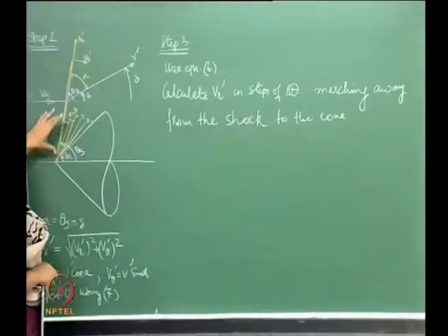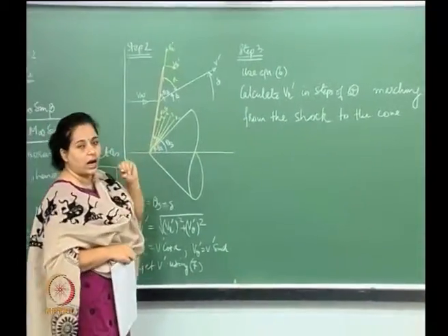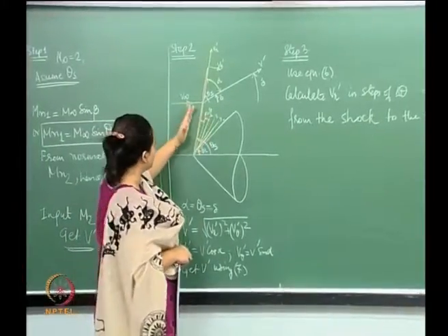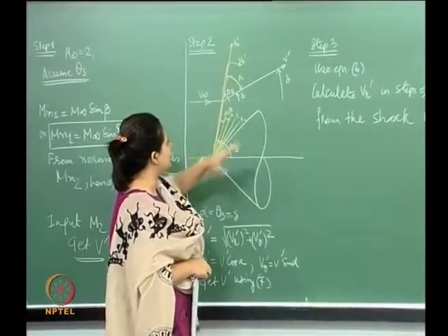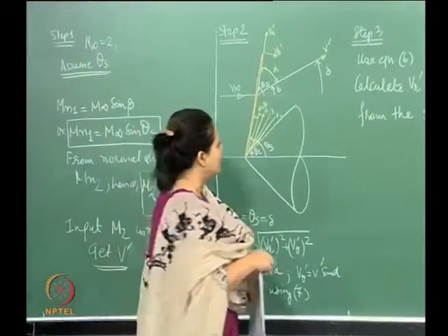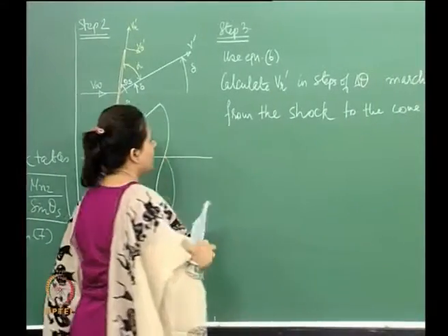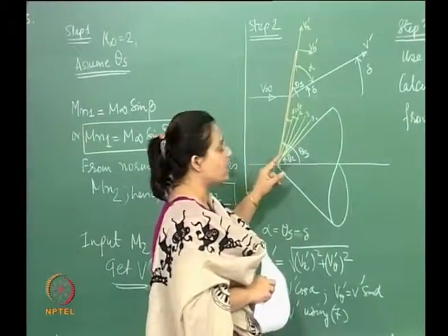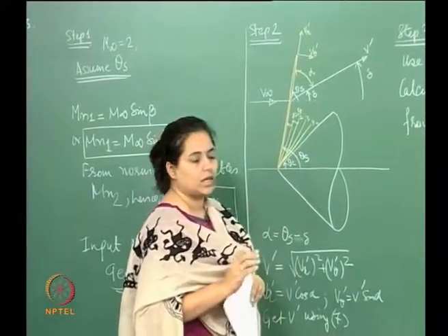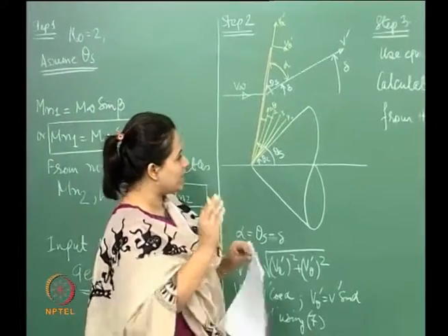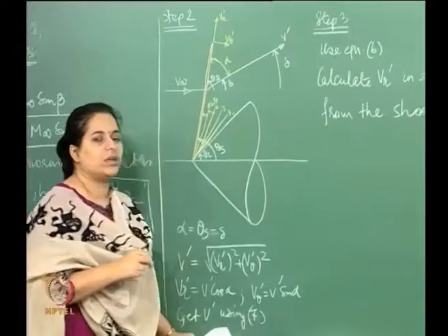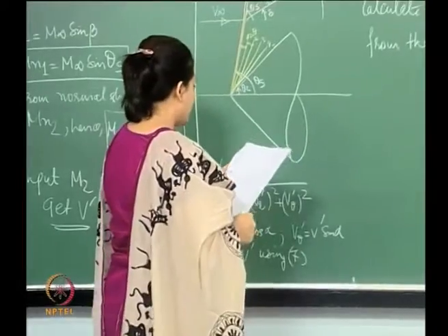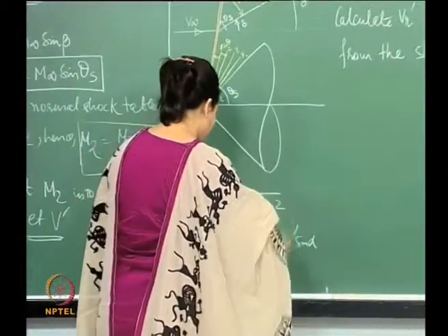Okay. So, basically which means that we will calculate the v r at various radial lines between the shock and the surface of the cone, right. So, when we do that, we will have to solve the Taylor-Maccoll equation. Now, that equation, as you have seen, is the complicated one. So, we will come back to that. So, what we will do is basically use a fourth order Runge-Kutta method when we do that. Okay. So, having done that,